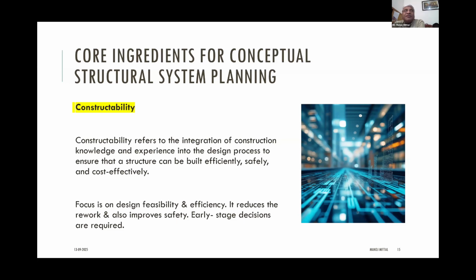So when we are doing conceptual design or planning of a structural system for a building, we need to understand how our construction knowledge and experience will be useful and how it can help in our structural planning stage. So our focus is on design, feasibility, and efficiency. It reduces rework and also improves safety. Early stage decisions are required for constructability. So we should not conceive or plan any structure system which is not constructible or which is difficult to construct, because it will be costly, time consuming, and may lead to a lot of contractual issues later on, apart from safety issues.